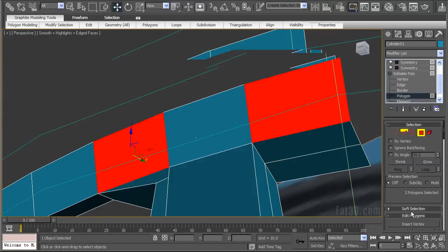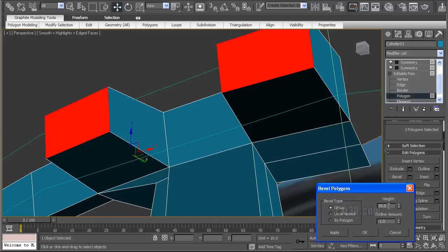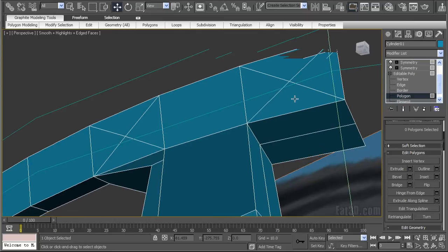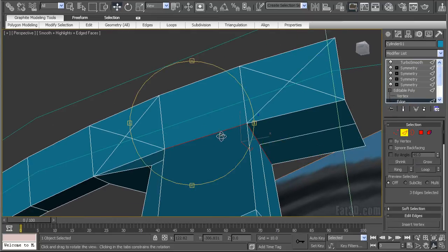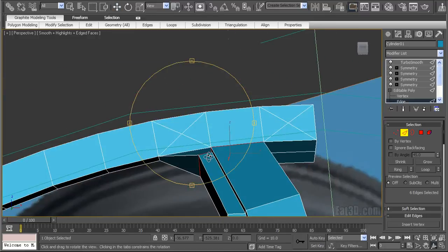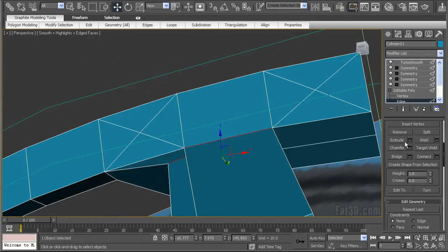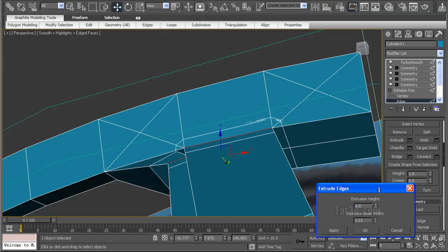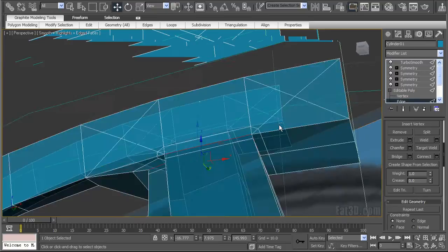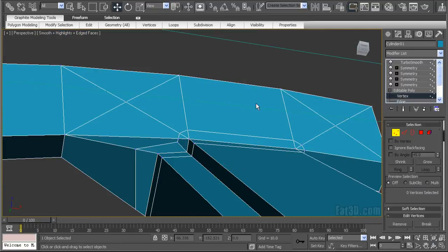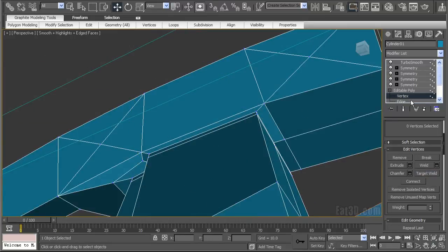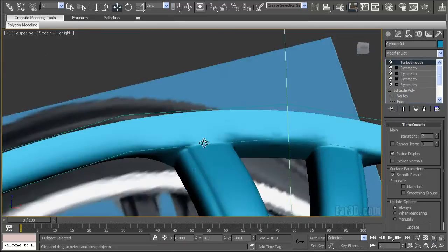Select this point, choose bevel, height 0, 0, and just collapse it. For me, like I said, it's a shortcut, and you'll see exactly why we did that. Select this here and use extrude. Okay, now we have extruded height. Next, use target weld. There we go.